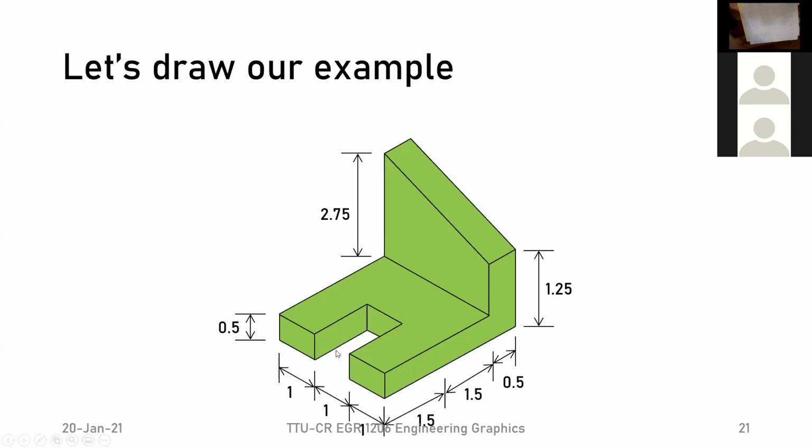All right. Now if we want to do the back side, the upward facing part, then we know that's 1.25 units from the bottom up. But in our drawing, we're already 0.5 up, so that means we have 3/4 left, because 1.25 minus 0.5 is 0.75. So 3/4 in our case is 3 boxes, because we said one is 4 boxes. So we have that height right there.